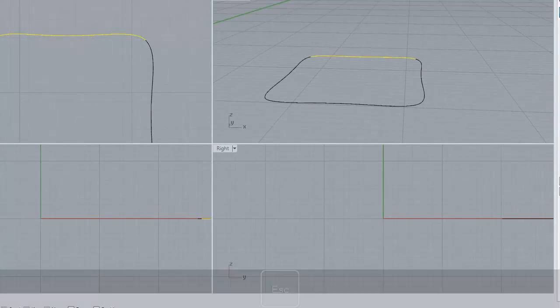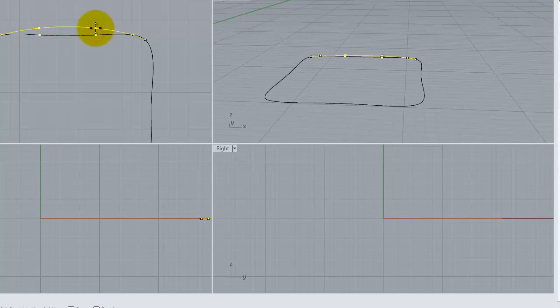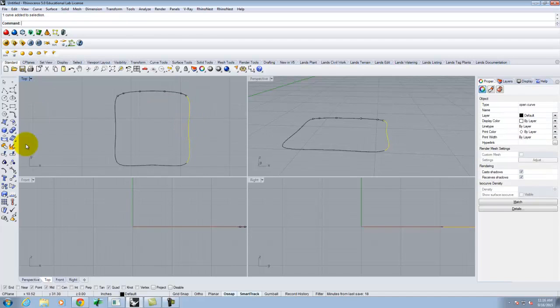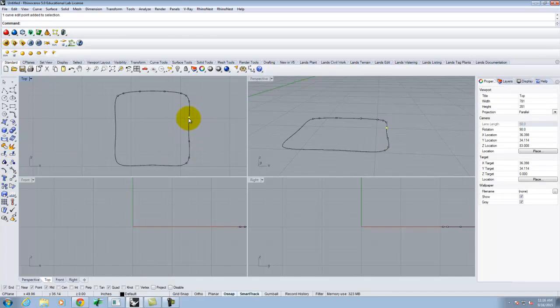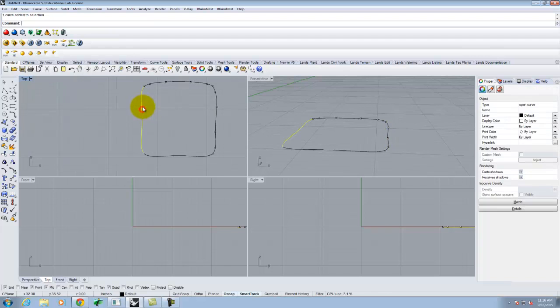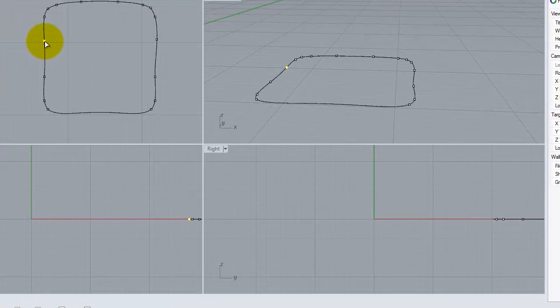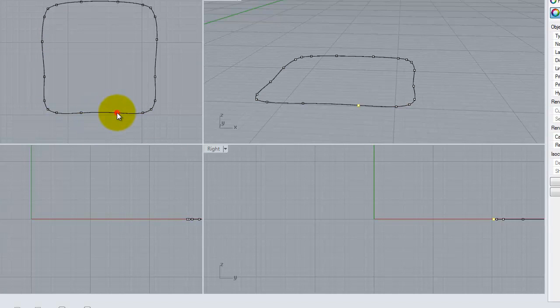Let me turn these points back on. And I'm going to push this out so that the back end of the cushion is actually bowing out a little bit. Right? And the side there, we could turn the points on. Just going to tweak it slightly. Let's move this out just a little bit. Turn this point on there. Move that out. So I'm causing the back end of the cushion to bulge just a little bit more. Front end here, I might push it so that it has even a little bit less. Let's move those guys in. Something like that.